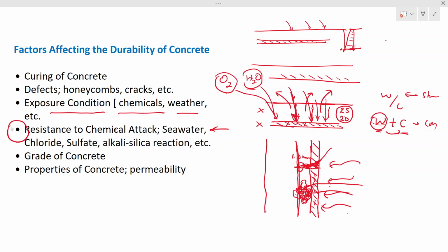There are criteria in the standard to select the grade of the concrete or the cement based on the resistance that we expect to reach. This is actually connected with the design life as well. So you select the cover, the concrete grade, cement content, water cement ratio, and the cement type based on these situations.